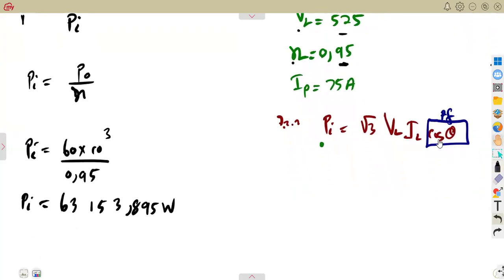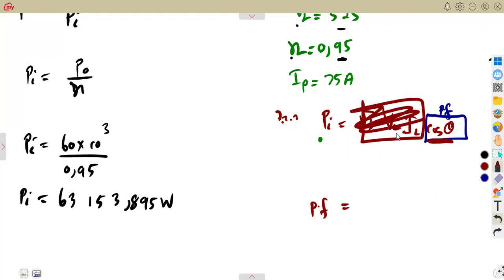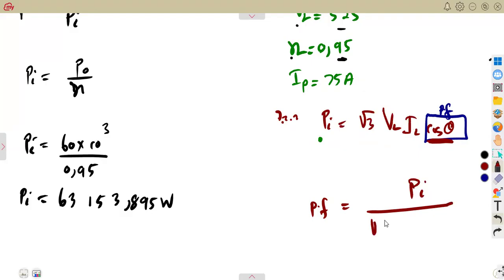All right. So with our input power, remember what you need is the power factor, which is the cos of theta. If we are to make it the subject, it means we're going to divide by the input power. So that is the input power over, we divide by, the square root of 3 times the line voltage and the line current. It's going to be the square root of 3 because we are dealing with the line.